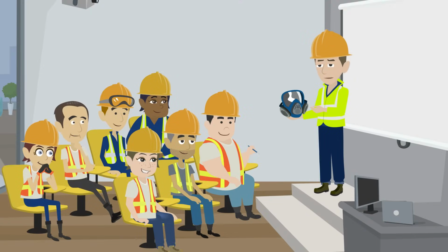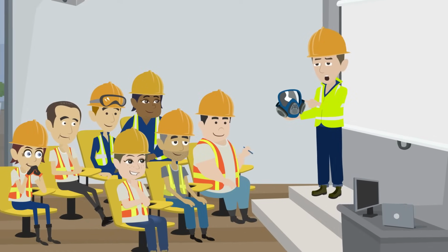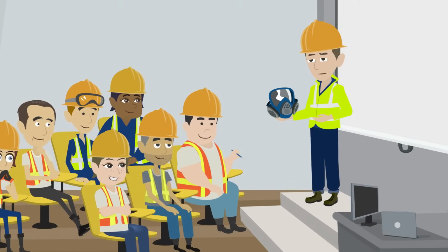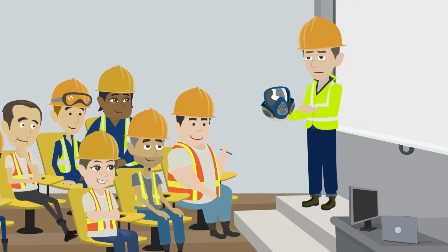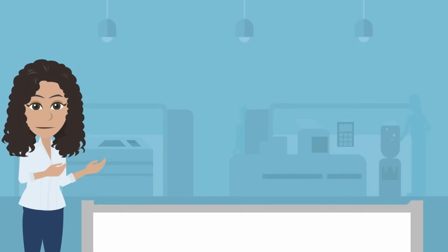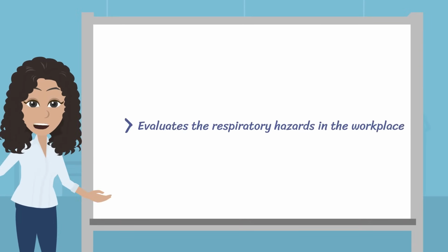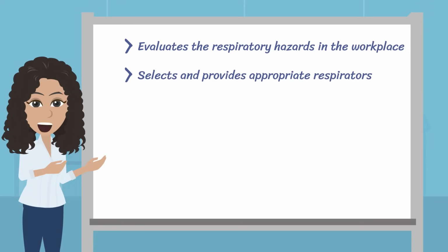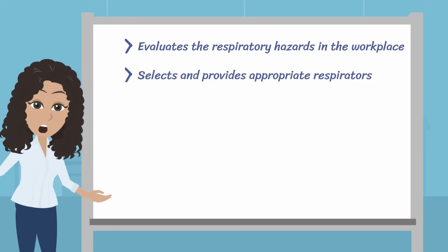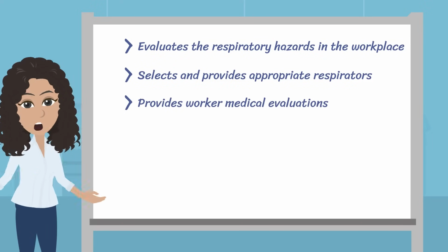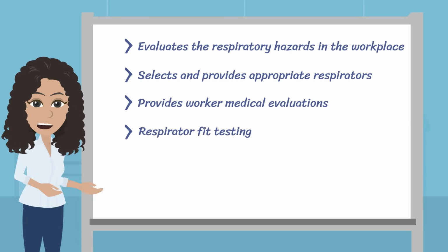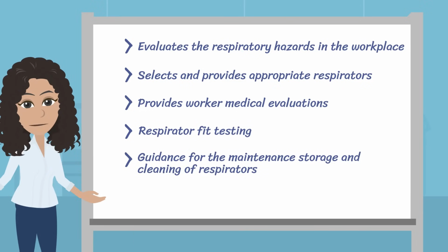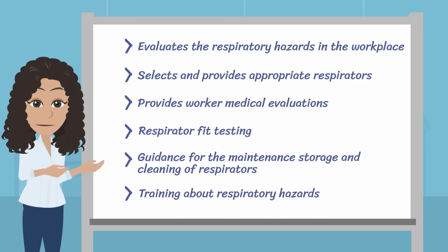The CFR 1910.134 standard requires the employer to provide effective training to employees and maintain a written program. The Written Respiratory Protection Program evaluates the respiratory hazards in the workplace, selects and provides appropriate respirators, provides worker medical evaluations, respirator fit testing, guidance for the maintenance, storage and cleaning of respirators, and training about respiratory hazards.